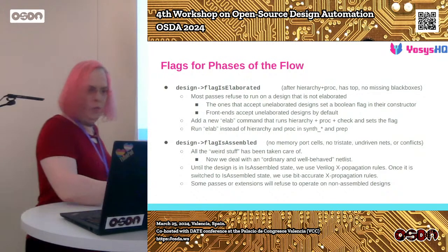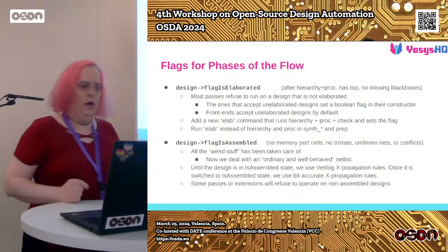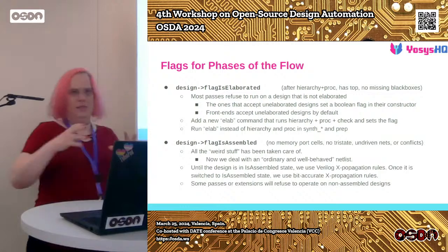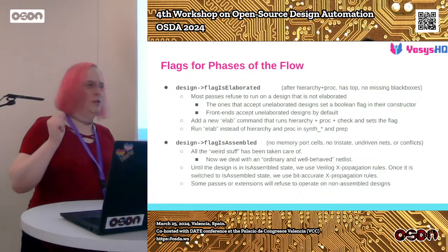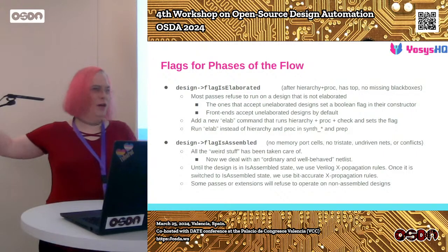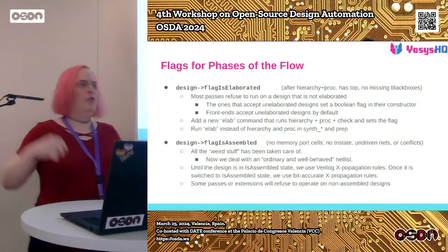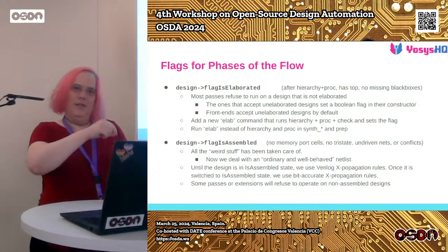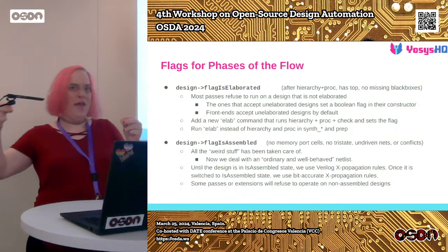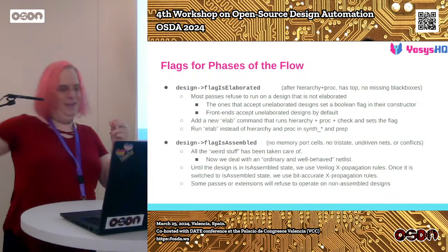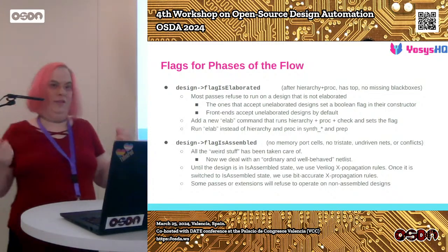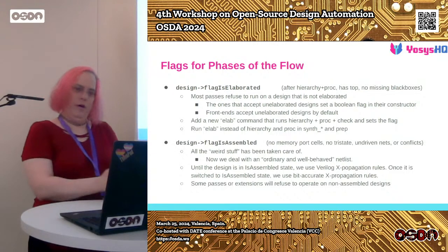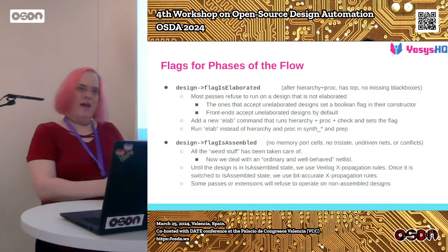One rules. So when you run optimization that is X aware, then you can propagate X's: if it's just one X, then all the output bits become X, even those output bits that technically would not be influenced by that input bit, because each input bit of the adder can only influence the output bit of the same weight, and then the ones that are higher but not the ones that are lower. But that's not the way that the Verilog standard works. So very early in the flow we have X-aware const propagation that implements these Verilog rules.